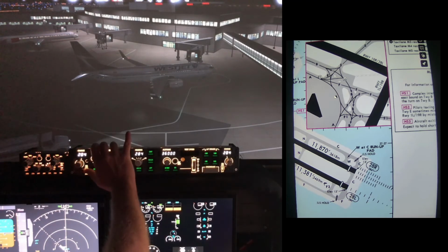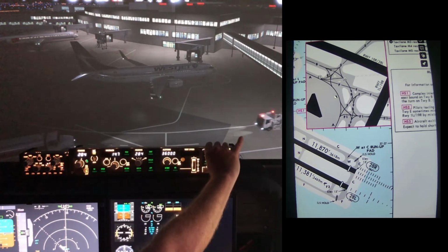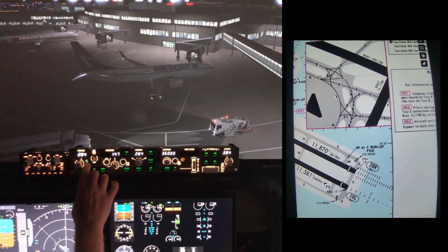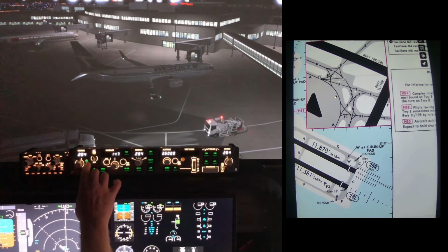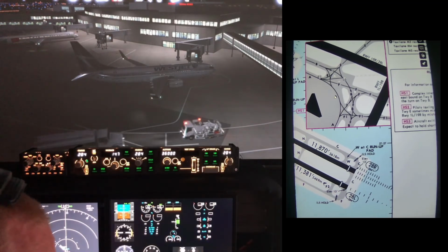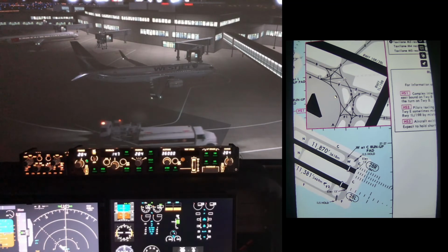We're also going to turn the flight directors on, left then right, and you'll notice the one on the left says MA, that's the active one. That's the master, with the co-pilot's being the secondary, because I'm the pilot flying from a captain perspective.